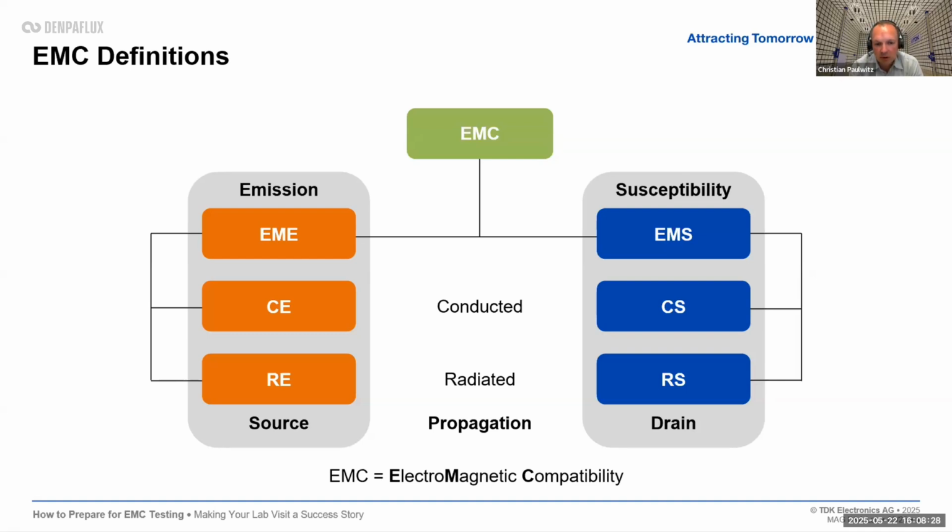For example, our typical conducted emission limits are based on a model to protect radio services below 30 megahertz. So in reality, in the typical real case, it might be a radio functional case, but we test it via conducted emission because it's easier to test and we can do better tests with better reproducibility. So that might sometimes be a bit different.